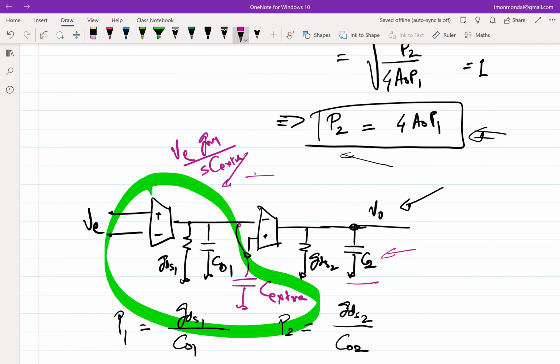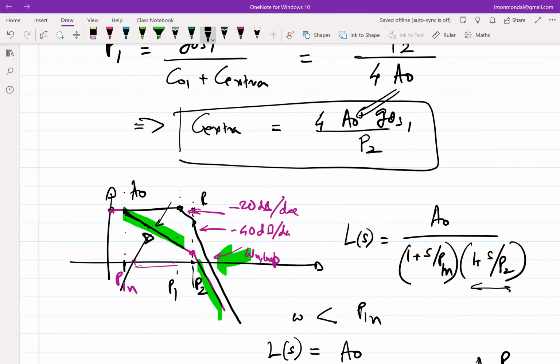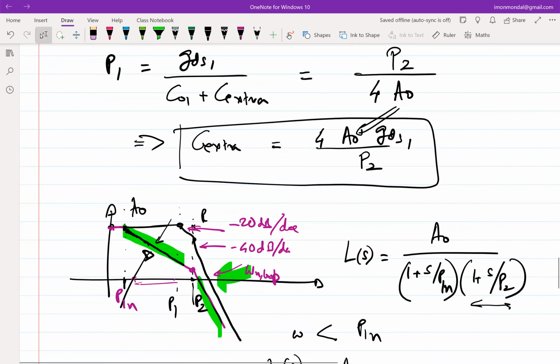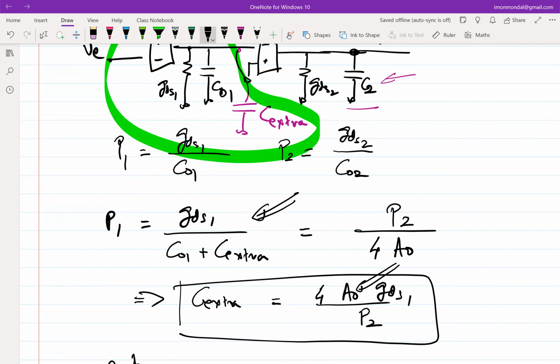Yes. So by looking at the Bode plot, we can decide whether the system is fast or slow just by looking at the omega U loop, right? Yeah. If it is high, then the system is fast. Small, right. Okay. And sir, how is the location of P1 getting changed by C extra? Yeah. So what is C extra doing? This is your P1, right? So sir, if the C extra is high, the location of P1 is close to 0, right? Right. But sir, the higher value of C extra makes the system sluggish, right? Yeah. That's what you are seeing also, right?